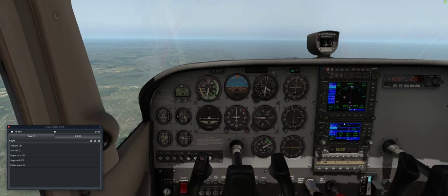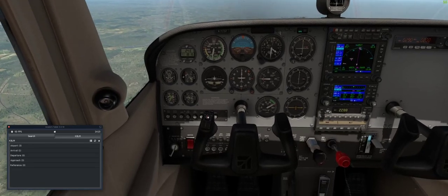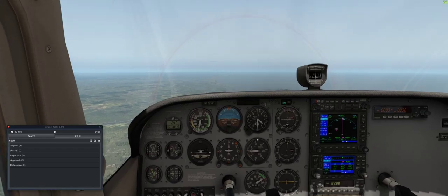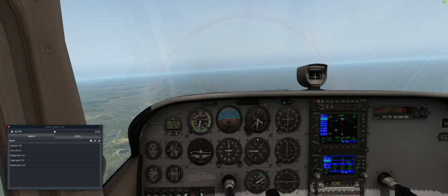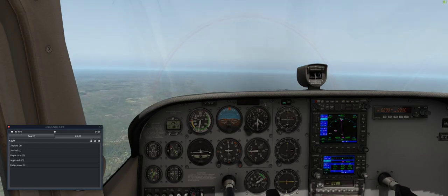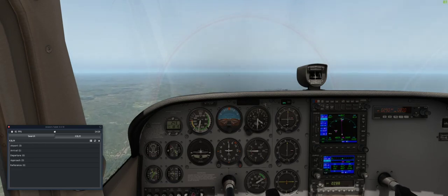If we were to turn off autopilot, there we just did. Now we're flying this by hand, and the aircraft was basically trimmed correctly. It's starting to deviate a little bit. Let me retrim it so that it flies straight and level, with hands off the controls, and they are off the controls.